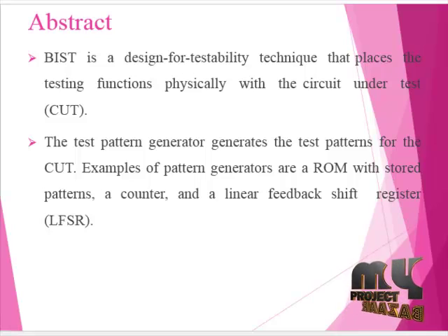We propose an LP test compression method that allows shaping the test power envelope in a fully predictable, accurate and flexible fashion by adopting the PRESTO based logic BIST infrastructure. BIST is a design for testability technique that places the testing functions physically with the circuit under test. The test pattern generator generates the test patterns for the CUT. Examples of pattern generators are a ROM with stored patterns, a counter, and a linear feedback shift register.